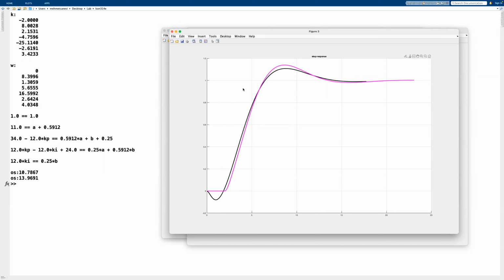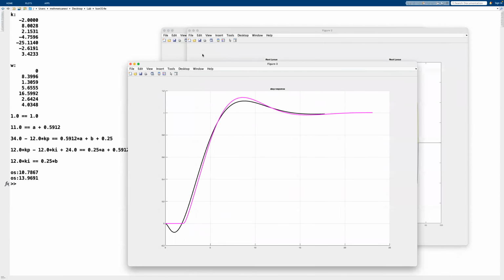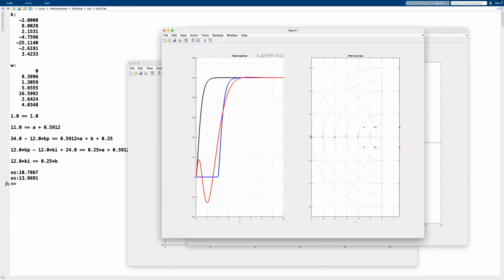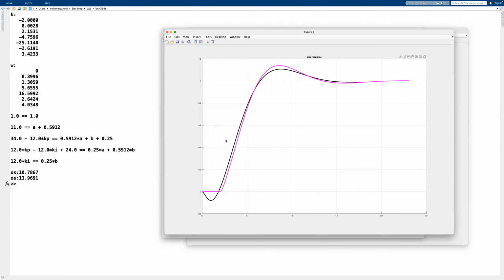Now, even if it does capture all the dynamics of the system, which we did see here, it needed a higher order one because this is the open loop. It still works for the closed loop and it works quite well. So this is refreshing to see because, well, if the response would be too off, then we need to basically increase the order until we will be satisfied with the result. If you're okay with 14% overshoot, which we should, by the way, we can just leave it at that.